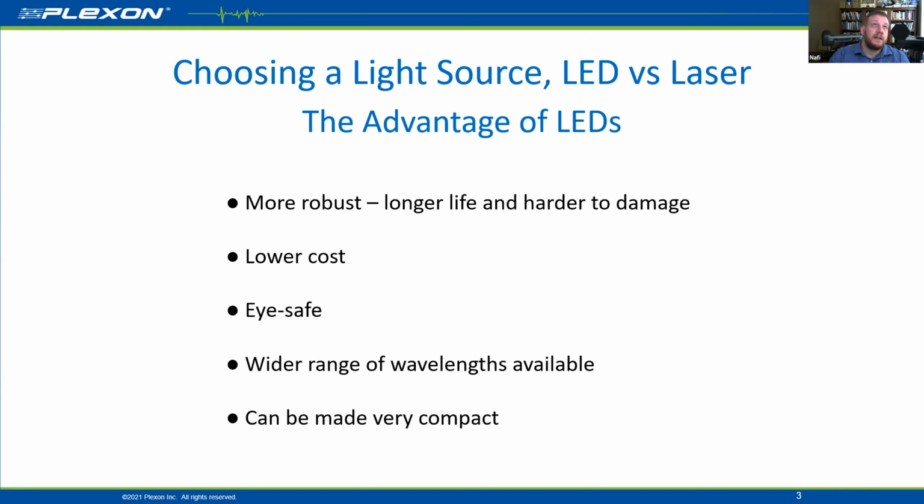The main advantage of LEDs is that they're much more robust, they last longer, and they're harder to damage and break. They're also lower cost. They're eye safe. The reason for that is LEDs do not use collimated light like lasers, which I'm going to go over a little bit about what that means. So if you accidentally turn on the LED and it shines in your eye, it's not going to cause retinal damage like a laser can. Also, LEDs have a much wider range of wavelengths available. And finally, they can be made very small and compact, which is really handy if you're going to have behaving subjects.